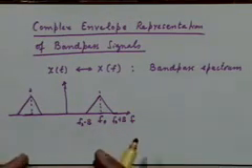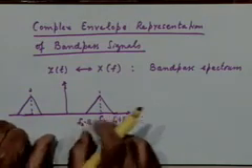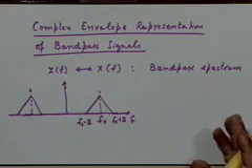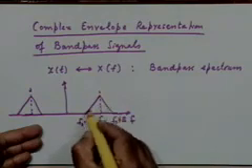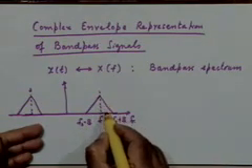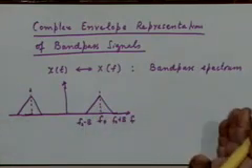What is required to be symmetrical is that the spectrum should be even symmetric around 0. That is a required property of the spectrum of a real signal. But there is no symmetry requirement around the center frequency that you may want to define. I could as well have defined the center frequency anywhere in this band. It really doesn't matter.